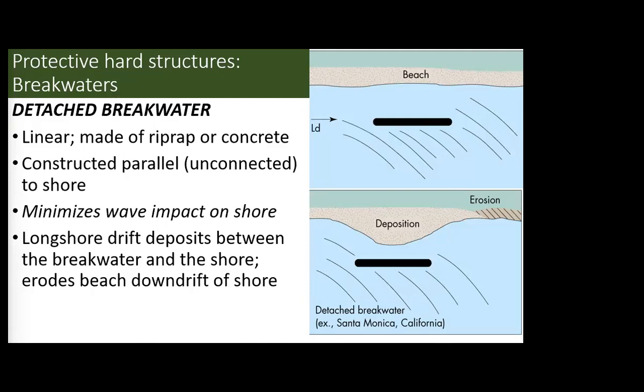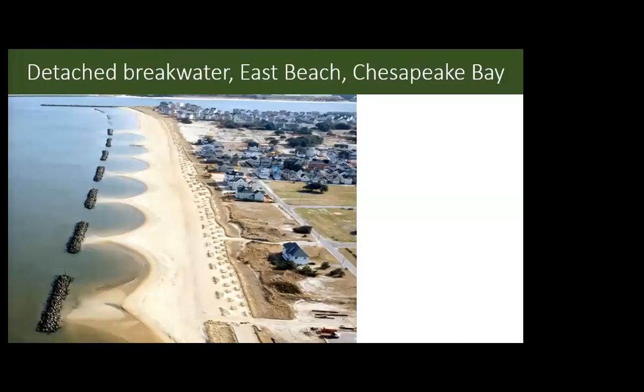So while we're still going to get some stuff on the outsides, we're minimizing that direct wave impact as a whole. So it'll eventually create these kinds of shapes along the shoreline. We're going to get a little bit of erosion in between them, but deposition on the back end of them directly.